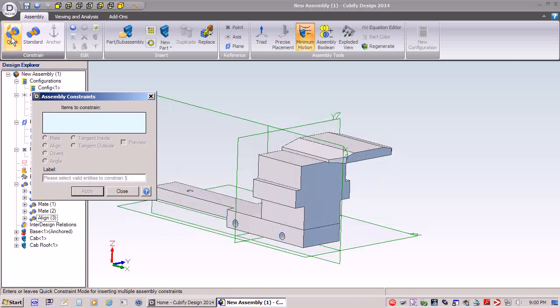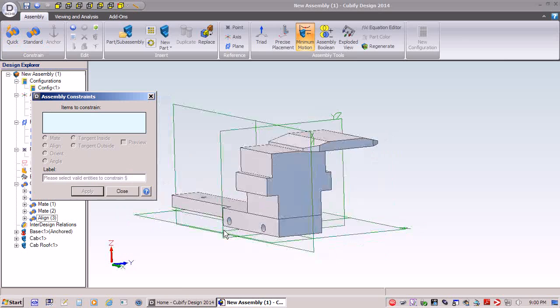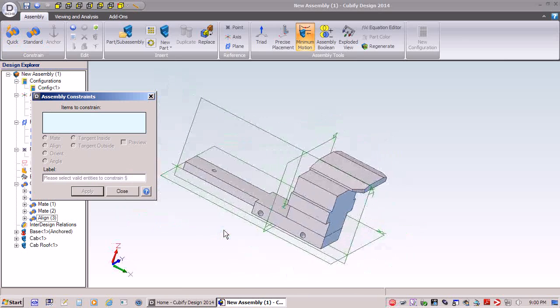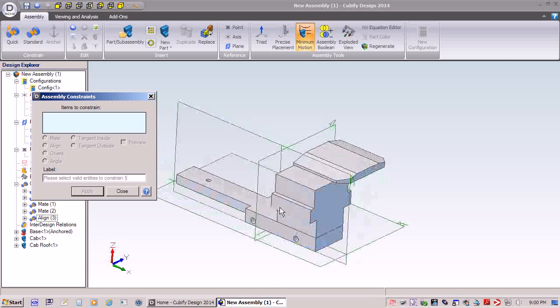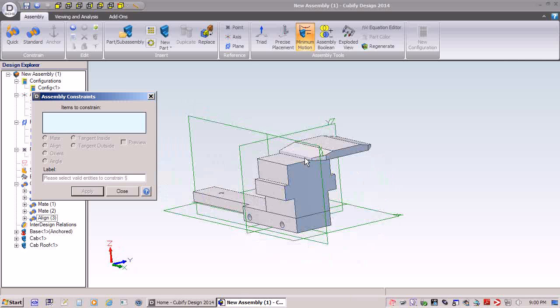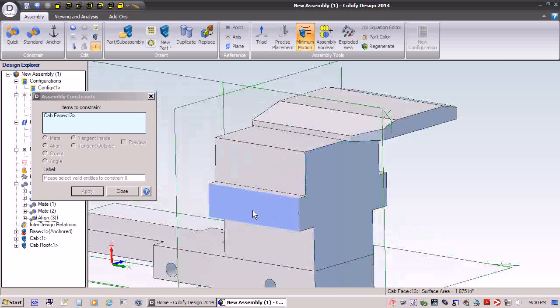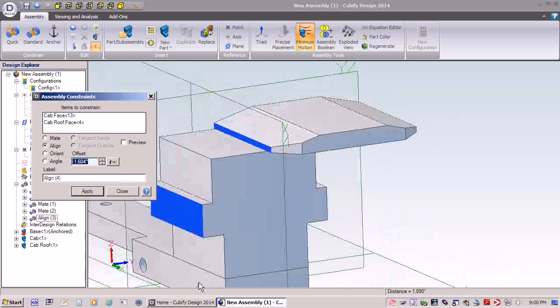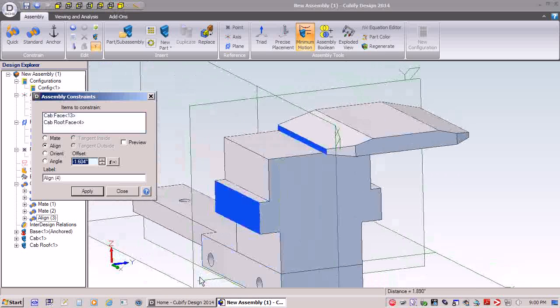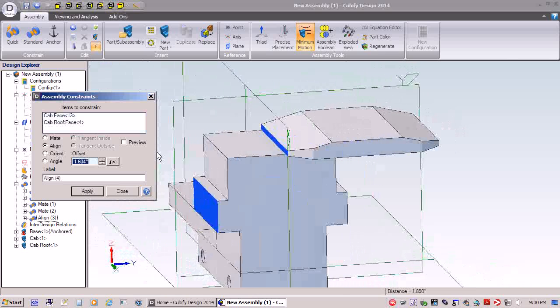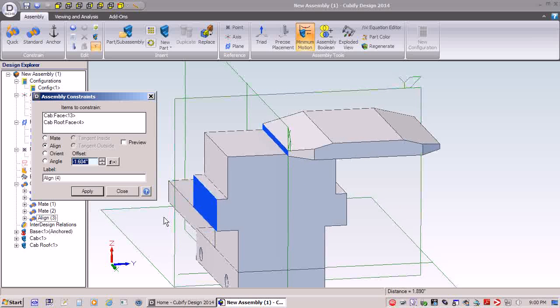So you notice there's a standard and a quick. That quick will try to figure out which of these options you want to do, and standard just lets you pick them. Originally I didn't know what I wanted, but now I'm starting to learn these good enough that I just like being explicit. So my cheat sheet is in reference to this, so that's why I'm selecting that. So the overhang is going to be about 1/4 inch.